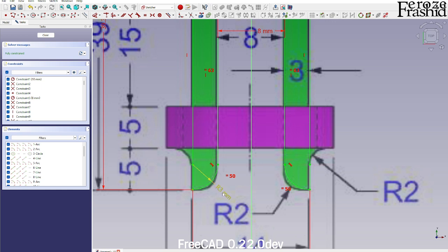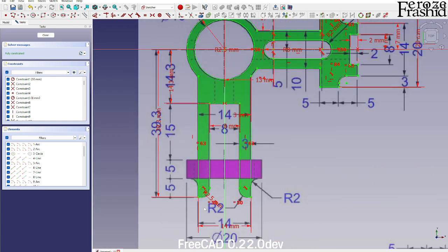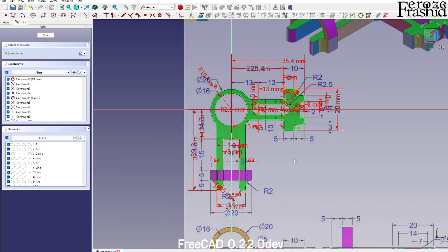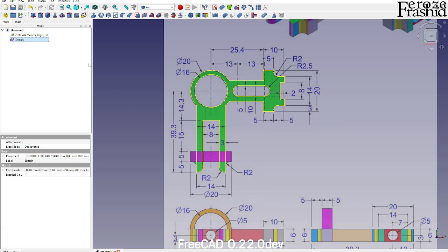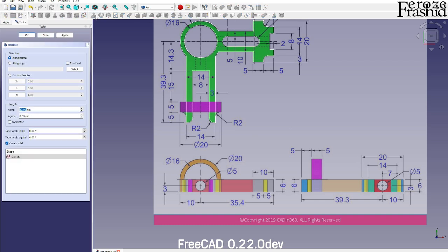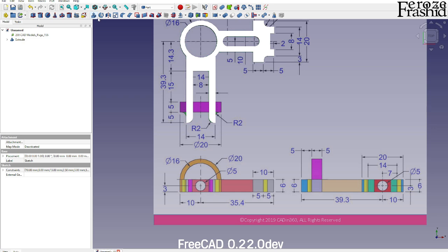No, it doesn't make sense. It doesn't match. So how about halfway between 2 and 3? Yeah. So this is going to be a 2.5 millimeter radius, obviously. So not saying that technical drawing is wrong, but it's not the best. Okay, we got the sketch, the basic sketch, and I want to extrude that for, is it 6 or 9? That's 6. Okay, that is going to be 6.